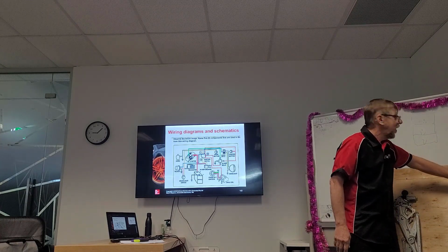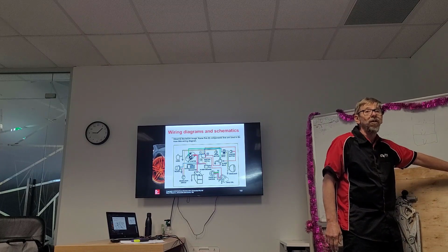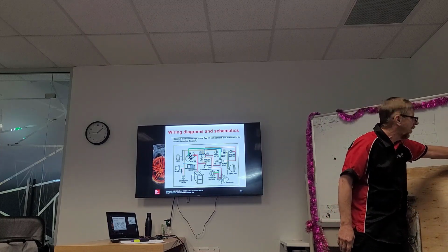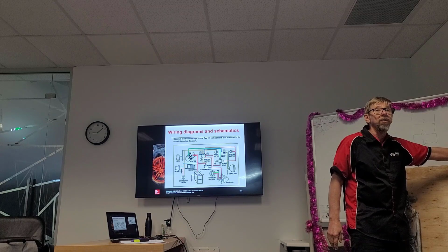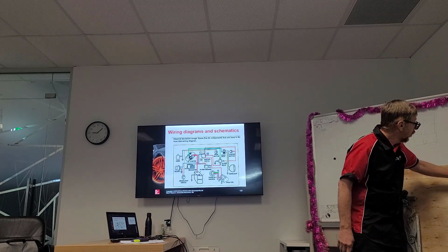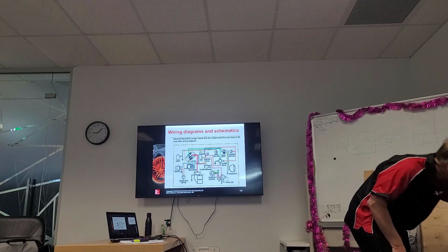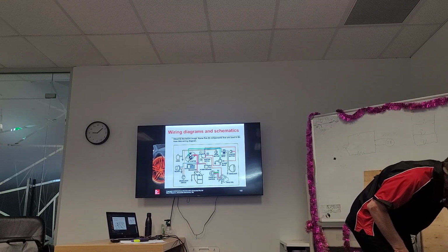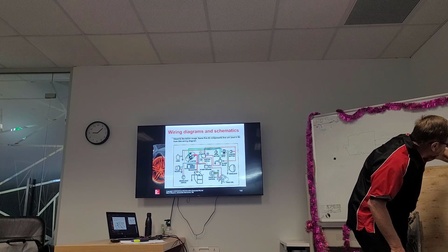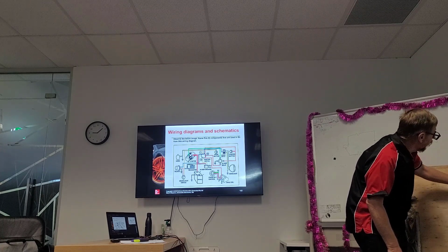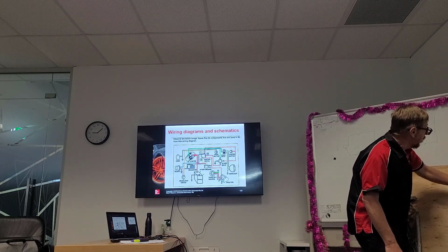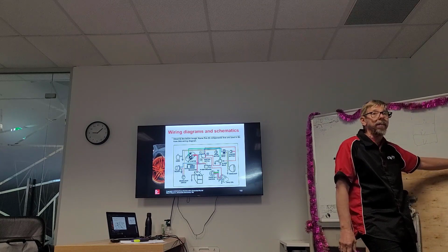That's like a fusible link. That's the main fuse going into the main fuse box. From the fuse box, we've got power. On this side, we've got a ground. And if we follow the ground up, there's a ground block here, and this side is connected to that ground block. On this side is connected to the power.